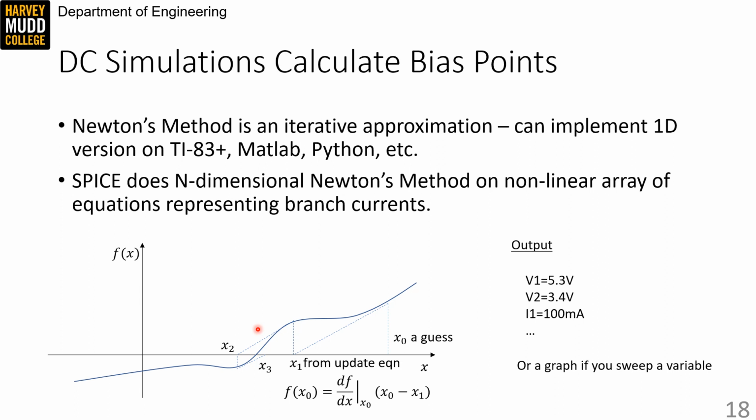However, Spice has done a lot of that implementation work for you, because Spice implements an n-dimensional Newton's method solver for systems of nonlinear equations. This is a useful trick, and it could potentially be useful for multiple disciplines, which is actually something that Spice recognized at the start of its existence. The name Spice is Simulation Program with Integrated Circuits Emphasis, suggesting that it was intended to be used in other domains originally, though it has mostly come to roost in circuits.